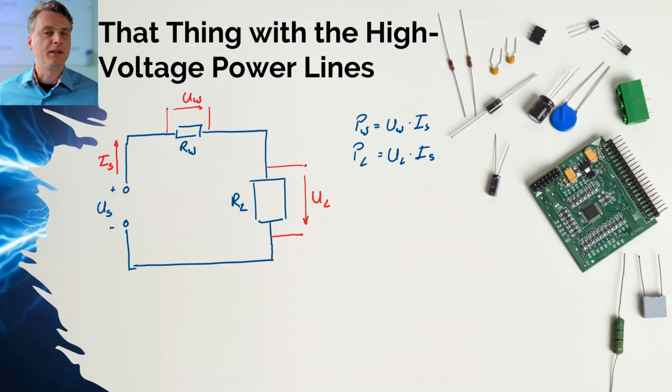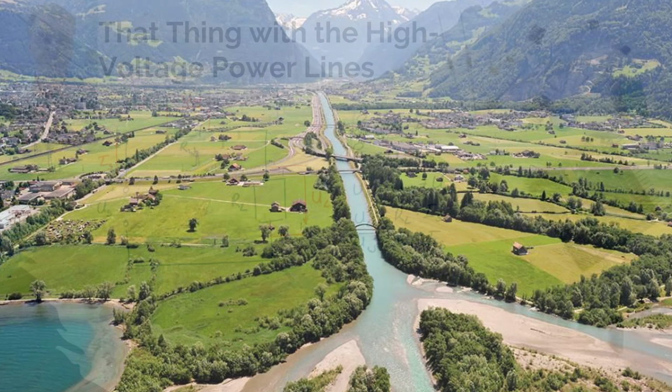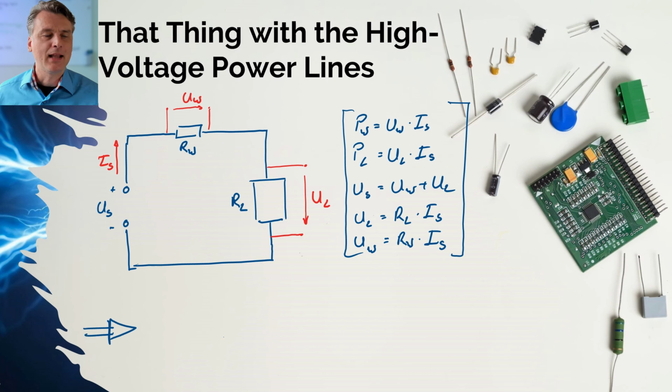If we now write down the equations we know, first of all, the power equations: that's the voltage drop U_W multiplied by the current, or the voltage drop in the load multiplied by the current. Then the supply voltage needs to be the sum of those two voltage drops because it needs to supply all the voltage drops. Finally, we have Ohm's law, U = R × I, you remember, and that applies for each of the resistors. Those are all of the equations I can think of and I need. Now, what do we do?